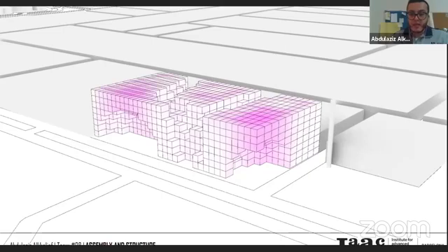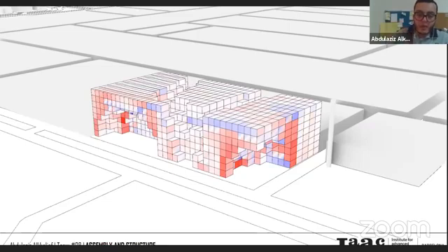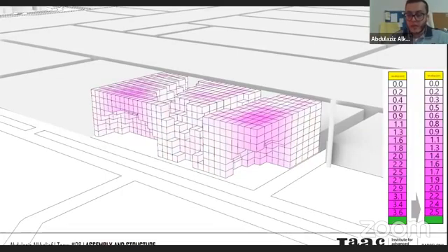Now it becomes again about the structural. I saw the cantilever above the shading area of the bazaar and public area had a little bit of displacement. The highest is 3.6 centimeters. Then I added bracing steels around the faces. I chose the highest utilization faces to add the bracings there. When I added them, it became 2.5. That is the difference in displacement between before and after adding the bracing steels.